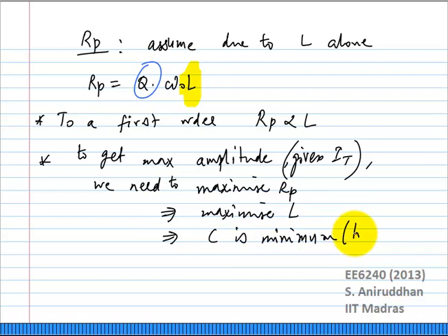So you will have a low tuning range, but let us assume for now that we choose a value of inductance close to the high end, such that we have a moderate tank capacitance value. What ties into this value of C is, if C becomes too small, the parasitic capacitance of the transistors and the inductor will dominate. So you have to be careful about this.